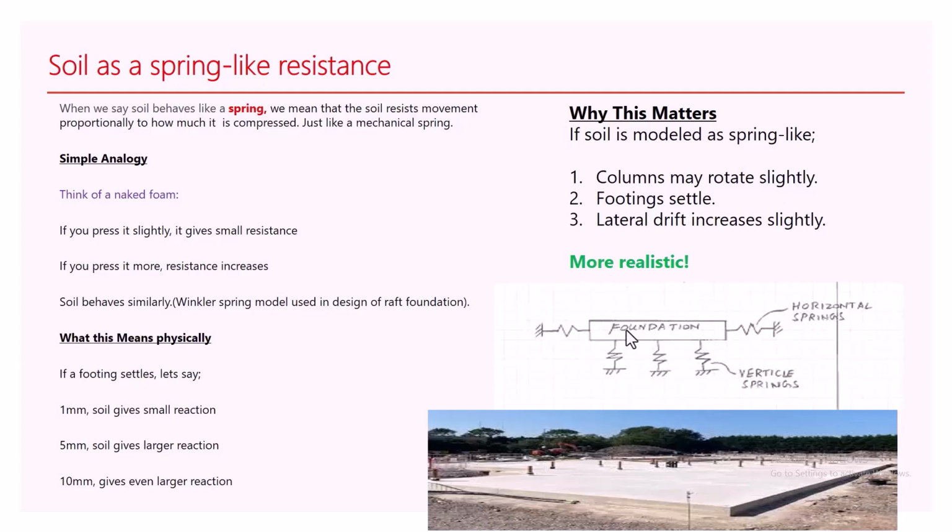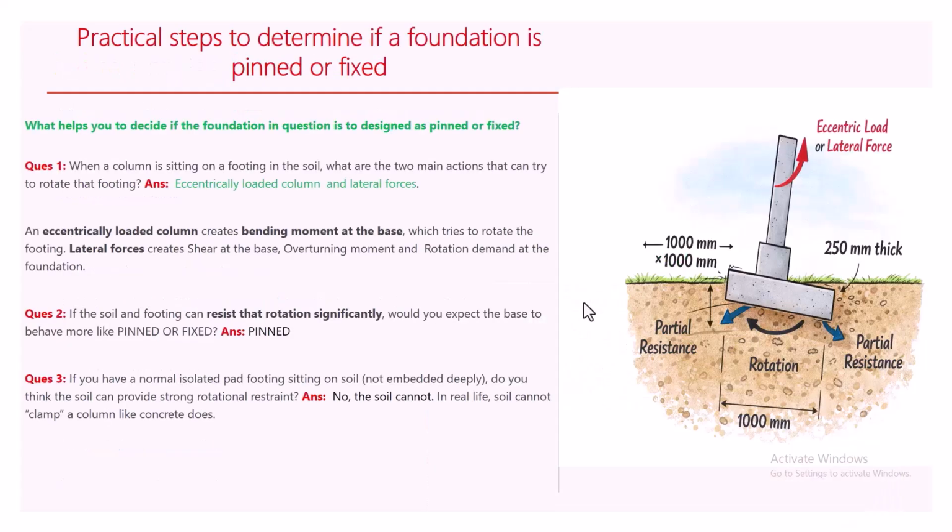So now, how do we determine if a foundation is pinned or fixed? How do you know this, or how do you identify this type of support? Because by identification, you model right, and when you model right, you have a realistic design. Not like when we normally use the default setting in the software as a fixed support. But most times, or sometimes, the foundation is not always fixed.